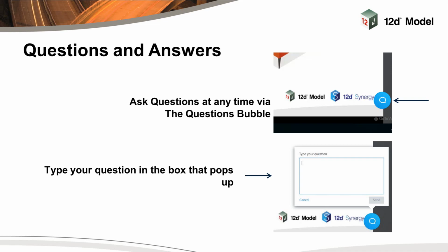So you can have as many frames as you like to provide the composition of what you actually want for your plotted output. Okay, and Mia and Victoria said, what if I have to flip or twist my view? You actually flip and twist the settings within the preview. I know there are a very small percentage of users of 12D that actually do change the view settings.